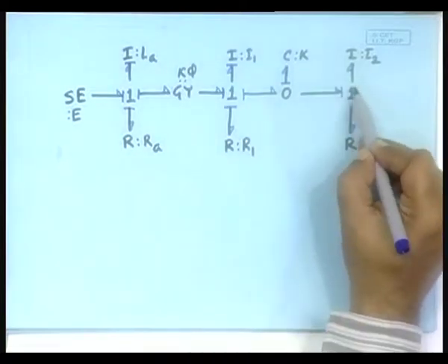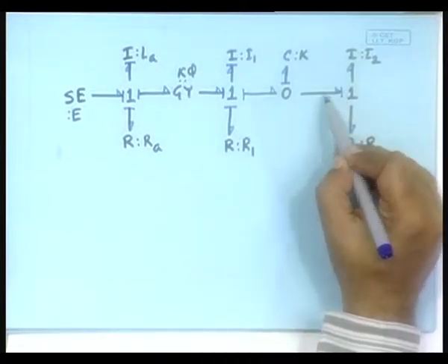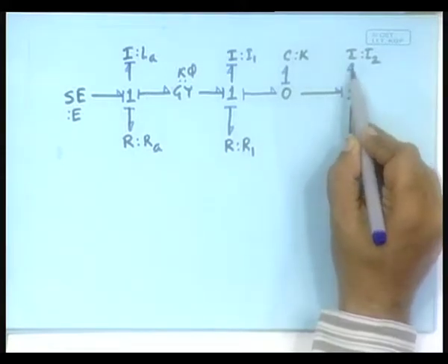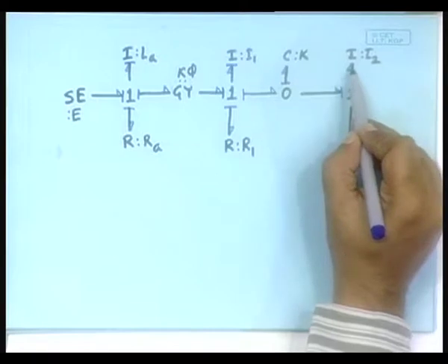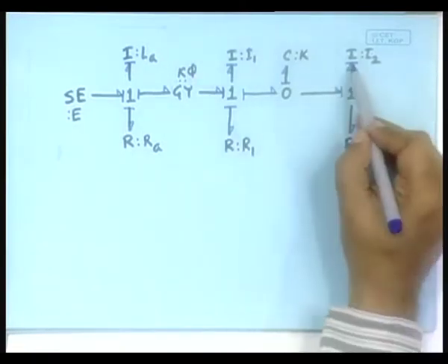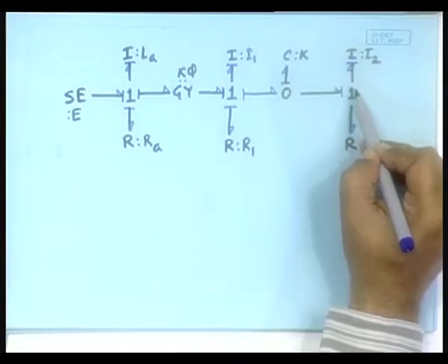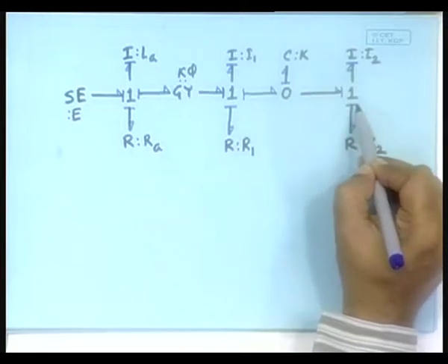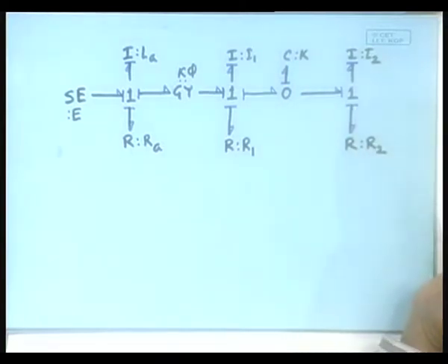And then I have a 1 junction in which the effort information is coming, and therefore it is not a strong bond. Here has to be the strong bond, because this is an I element whose causality should be like that, and this brings in the flow information, which then must be distributed. It is already distributing this side, and this one should also be distributing. That completes the story.